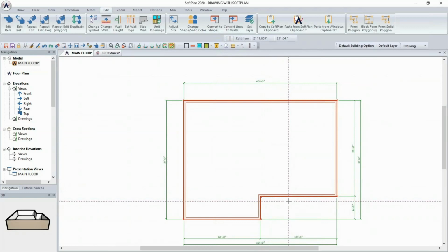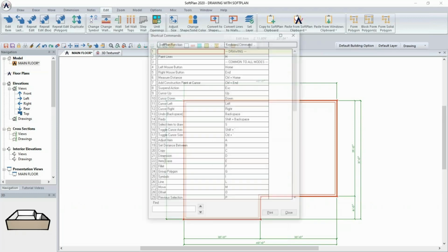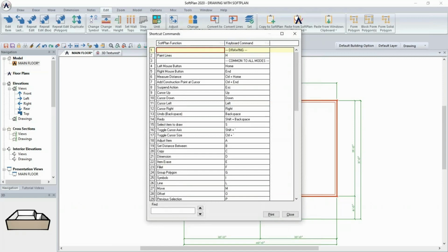A cleanup can also, for example, modify positions, or what we call offsets. Can also join cabinets together. And there are a number of other aspects of where the cleanup will then do things to clean up the drawing. I always say you can never clean up the drawing enough. Control C is also the keyboard shortcut for cleanup. I can press it here, you don't see anything happen because I've already done it. But if you're curious, a control question mark does bring up this shortcut list.